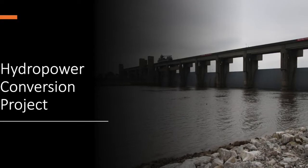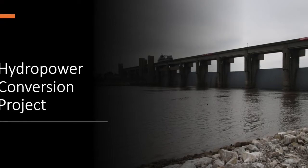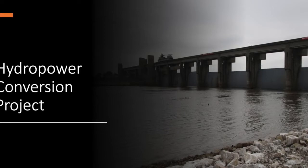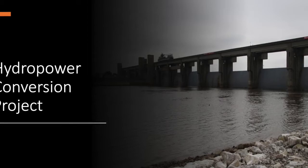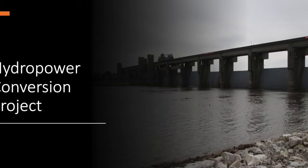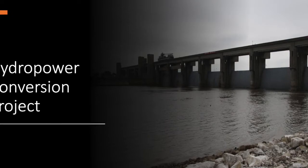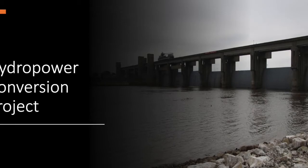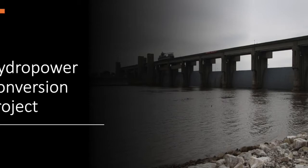We estimated that it has the potential of providing 30 megawatts of power based on the assumption that we would be able to redirect around 10% of the river's flow through additional channels. The small percentage of redirect was made due to consideration of the original purpose of the dam in the 9-foot channel project. The fluid dynamics for the project were analyzed and were used to determine the design of turbines needed, as well as the channel sizing. Cost and timeline estimations have also been developed for this project.